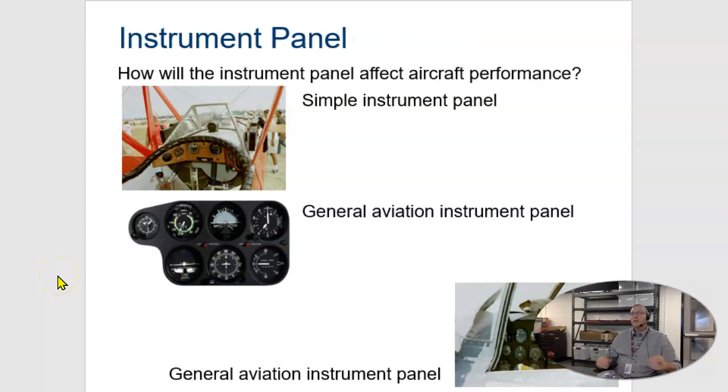And this last slide, it talks about the instrument panel. One of the design features that has to be really considered in the development of an aircraft and the control panel is it has to be easy to understand at a glance. If you have to search around and think about things, you have problems. Like in the space programs in the 60s, what they figured out is if you made the dials where when they were in the right place, they all made a straight line, it made it much easier to determine if there was a problem and where it was, rather than just having dials everywhere pointing any which direction. If they all lined up and one was out, you could tell you had a problem.